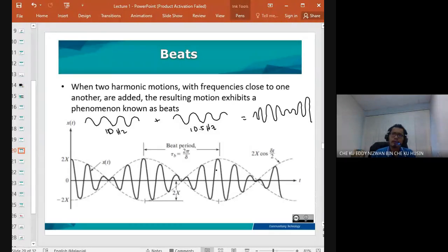For this solution you have to do rectification. Because you cannot control the speed, you have to isolate the motor, to ensure that the vibration from one motor doesn't transmit to another motor. By isolating, the vibration from one motor is not transmitted to the other. That is the common solution in industry.